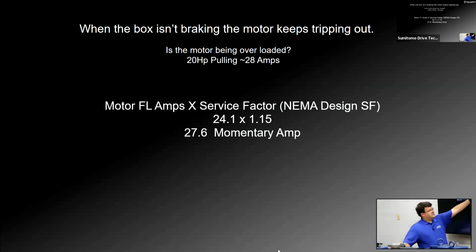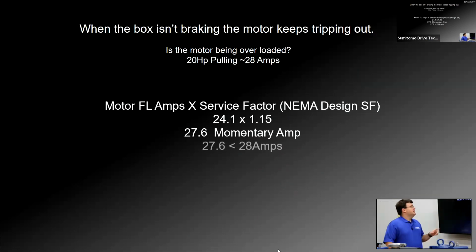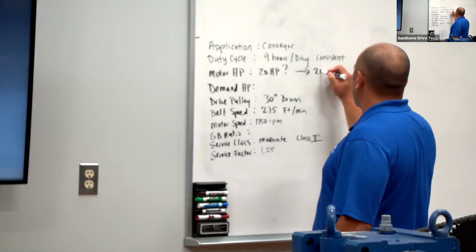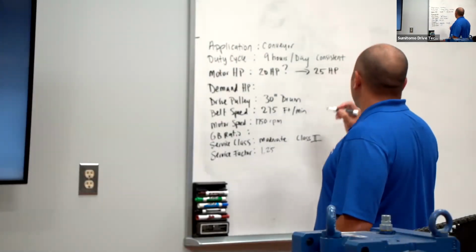He's pulling consistently 28. So it's safe to say this motor is undersized. So we're going to kick it up to the next larger size motor, which would be a 25 horsepower. So we'll change our 20 horsepower up to a 25, just because we know it's safe. This one's having an issue, we want to be safe. We don't want to keep having that issue pop up.